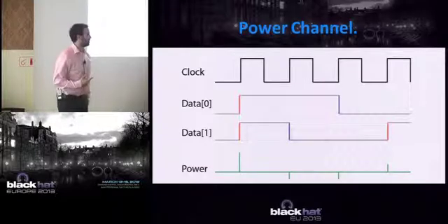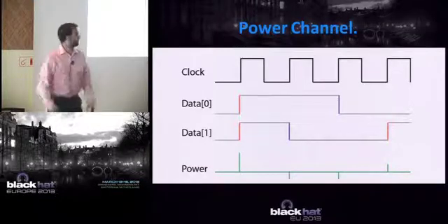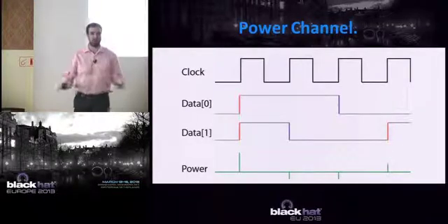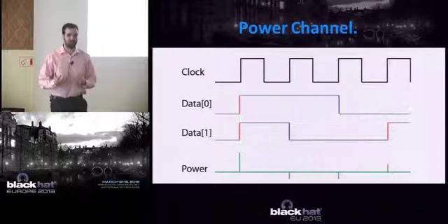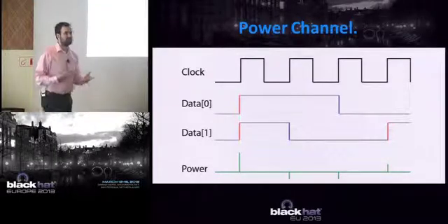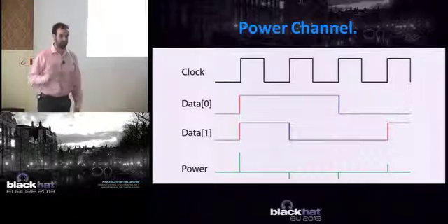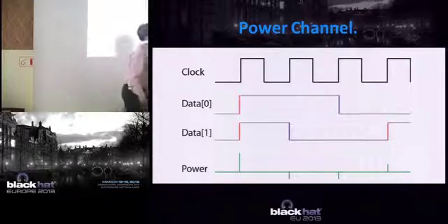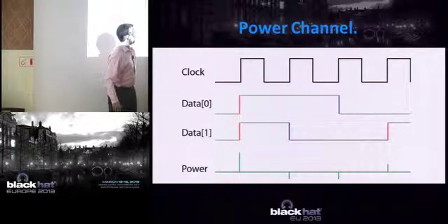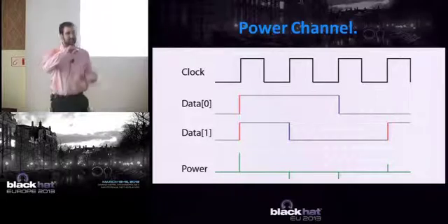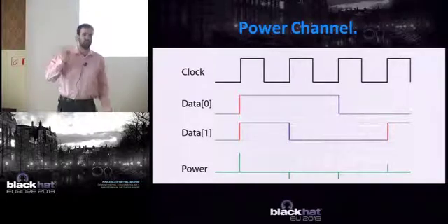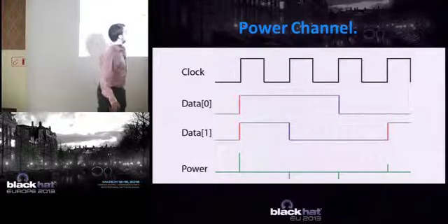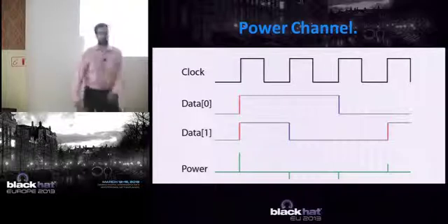Where this comes from is the buses do something called a precharge. You can imagine if the data bus switches from all ones to all zeros, this would be the worst case power consumption. This would require the most charge. Your worst case is going to limit your device in terms of speed and things like that they can go over the data bus. So what they do is in between these two states, it's pre-charging it to halfway. So it's always putting it to this half state. To go from this half state to either positive or negative is going to take half the energy. So now when we go from all ones to all zeros, it's actually going to this half state in between and then goes to all zeros.